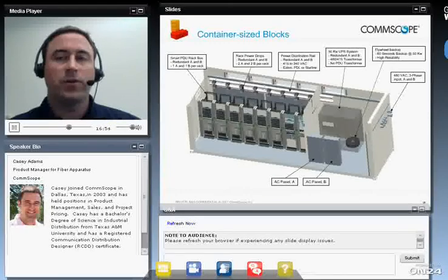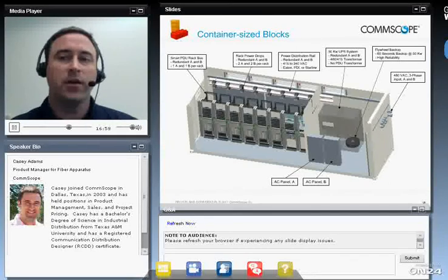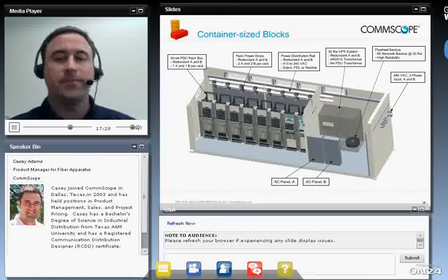For the opportunity where internal floor space is no longer an option or the design calls out for a container block, the modular approach works twofold here. First, at the container level: the design of the container farm, the types of power requirements, the amount of pads or platforms needed, and the connection points to that container. Inside the container, it moves back to a traditional data center architecture on a moderated scale. There's the A and B networks to design for, the power to those networks, and redundancy, as well as the power backup. This may be the most dramatic type of living infrastructure that we see today.